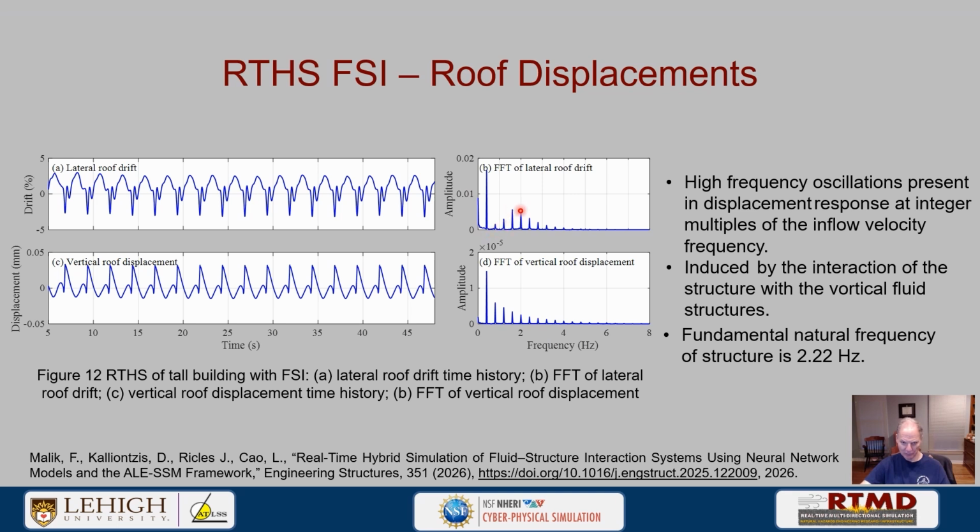This rises before it dies. Why is that? Well, the answer is right here. There's a fundamental natural frequency of the structure at 2.2 hertz, right around here. And this is where we're getting dynamic amplification of the motions of the structure. So this is the dynamics and fluid structure interaction.